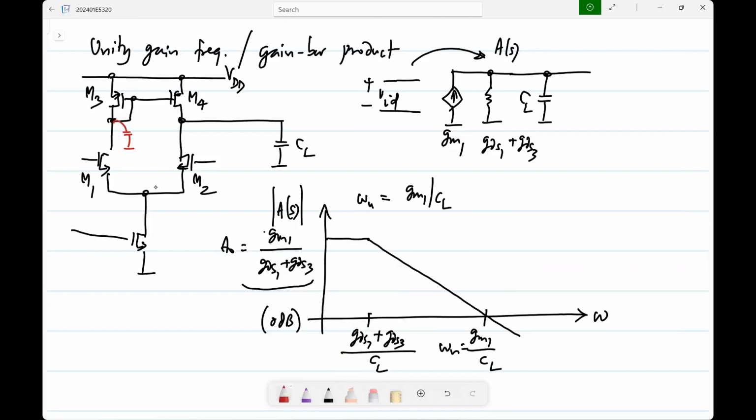You can have some parasitic capacitance there, and also you will have it here. Remember, this is not a symmetrical circuit, so this voltage is not incrementally at ground, even with fully differential inputs. If the circuit is symmetrical, then this will be at ground, so no current flows through that. In this case, the circuit is not symmetrical, so that also can have an effect. But I won't worry about that. I'll only look at this one.